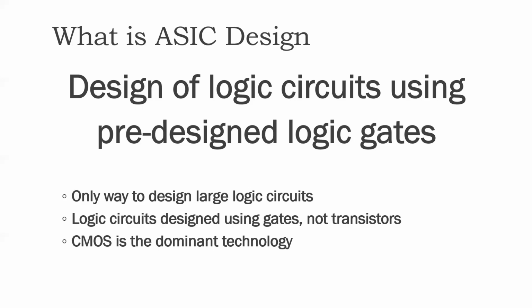So in ASIC design, we rarely deal with PMOS and NMOS transistors that are the foundation of logic circuits. We don't think in terms of transistors, we think in terms of gates. In general, CMOS is the dominant technology in ASICs, but not the only one. The key aspect of ASIC design is that the design is with logic gates and not with transistors.